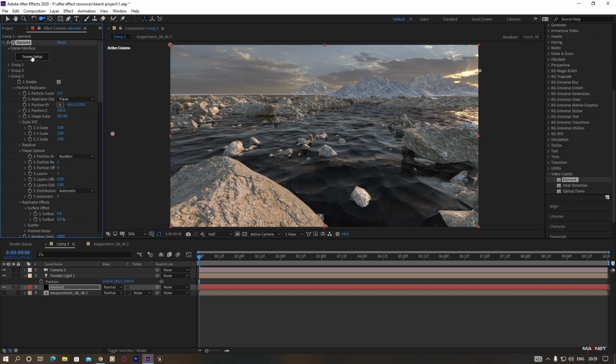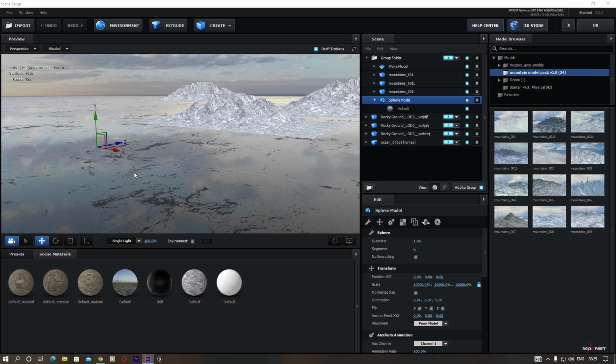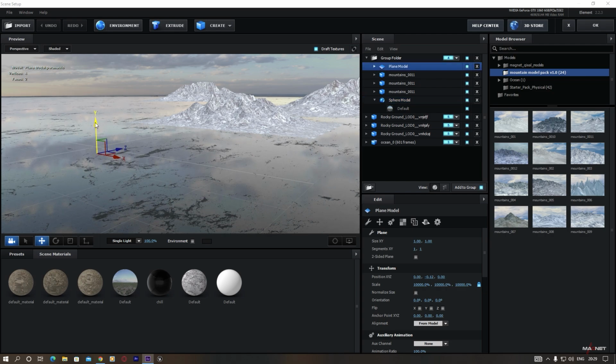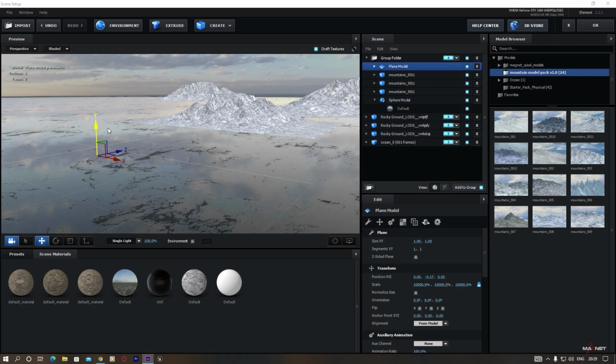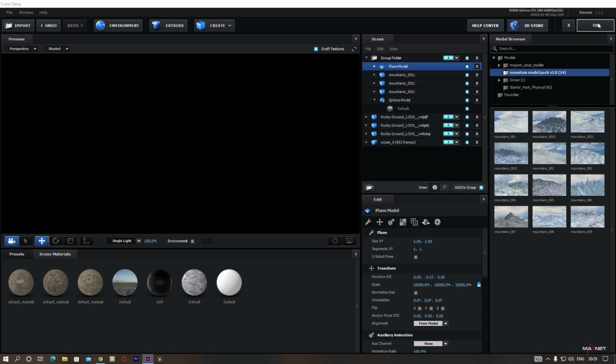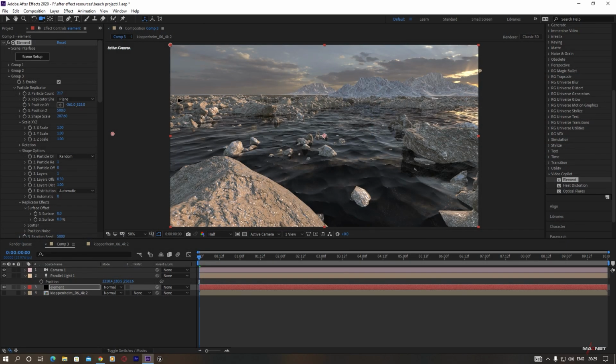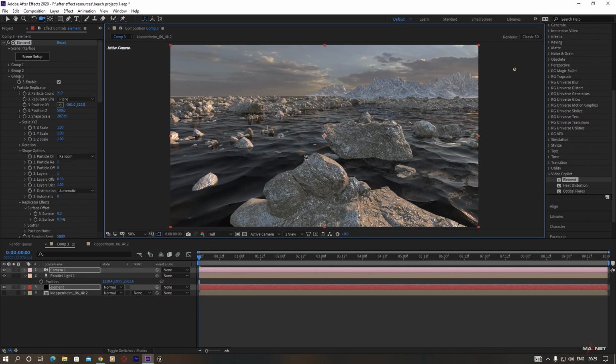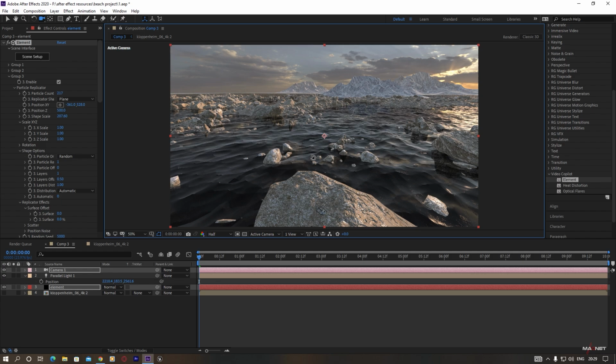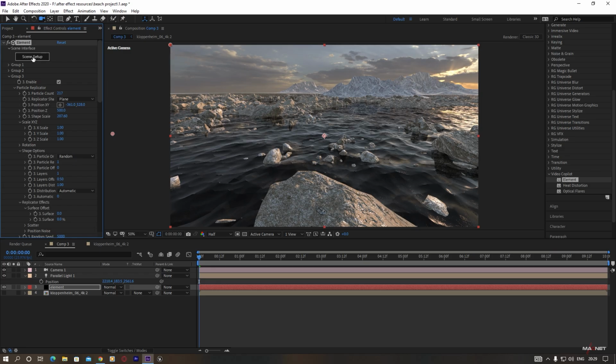And then again also go to the scene setup here, and then select this surface here, and maybe we put it a little down here, and then we hit OK. And now you can see that the issue of the horizon is gone. So it creates a nice result for our scene. Okay, so this is how you can build the scene, and you can also duplicate the mountain multiple times here and there. So maybe we can do this now.